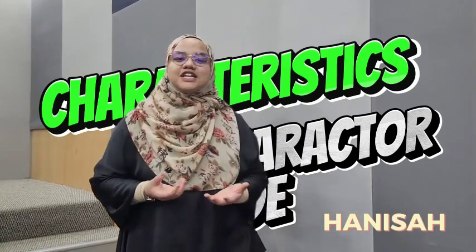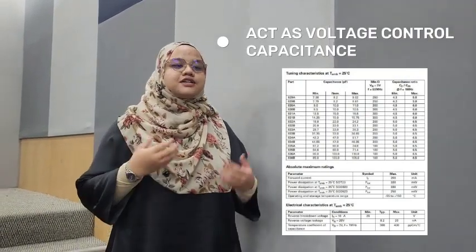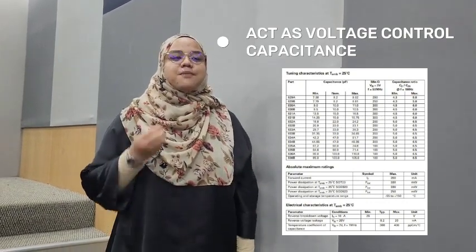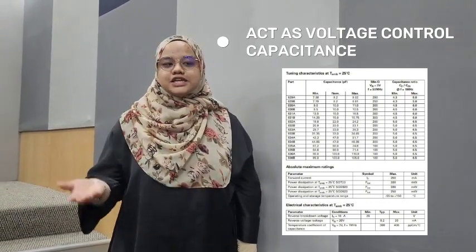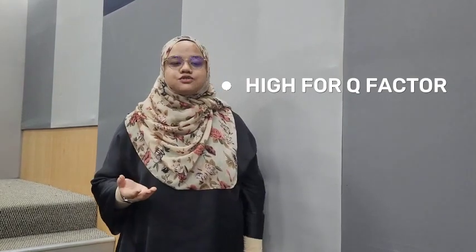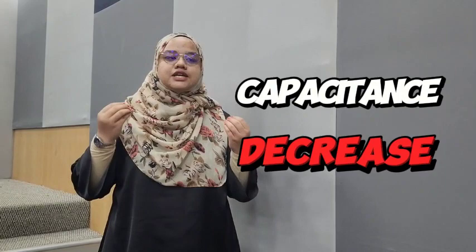The characteristics of the varactor diode. First, the varactor diode acts as a voltage-controlled capacitance. It is used in places where a variable capacitance is required, and the capacitance is controlled with the help of voltage. Second, the varactor diode has a high Q factor. This means how effective the component is at storing and releasing energy. Third is the relationship between capacitance and reverse voltage. It is a non-linear graph. When the capacitance decreases, the voltage will increase.